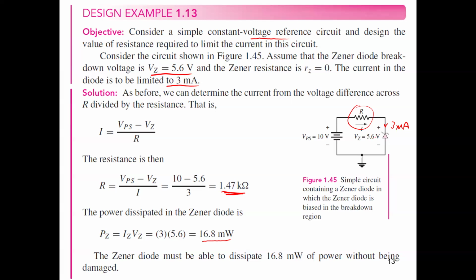So now, guys, we can use this circuit like that, and the output here is going to be 5.6 ampere, or sorry, 5.6 volt all of the time. So this means we can use it now as a voltage reference. We can use this now as a voltage reference in a circuit or in a power supply. Okay.